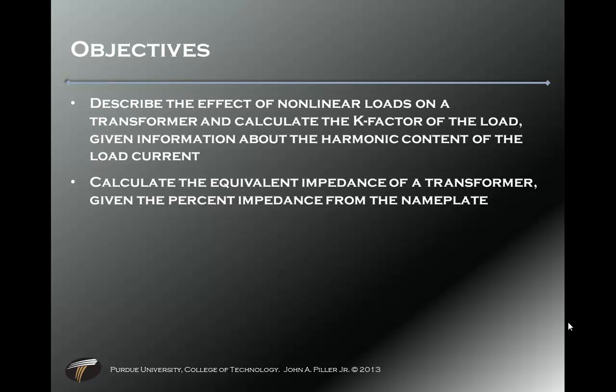We're going to talk about nonlinear loads on transformers and the K-factor, how to deal with those nonlinear loads. Nonlinear loads cause excessive current. Nonlinear loads add that third harmonic issues to us. Calculate some equivalent impedances of transformers given the percent impedance from the nameplate.